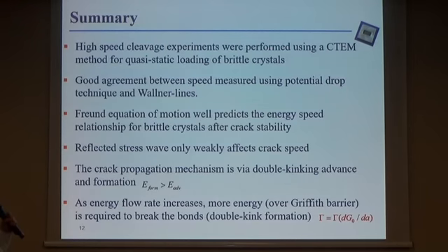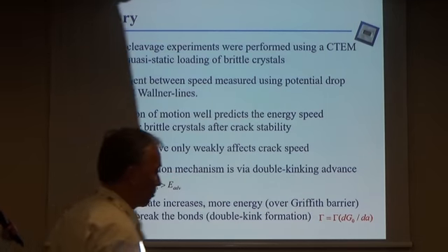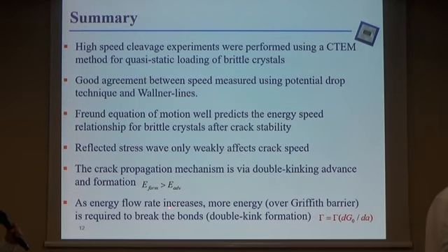So I will summarize. We have performed high-speed cleavage experiments using the CTEM method for quasi-static loading of brittle crystals. We show a good agreement between speed measured using the potential drop technique and Wallner lines. We show that Freund's equation of motion well predicts the energy-speed relationship for brittle crystals after crack stability, and that the reflected stress wave only weakly affects crack speed. The crack propagation mechanism is via double kink formation and advance. And as the energy flow rate increases, more energy is required to break the bond.